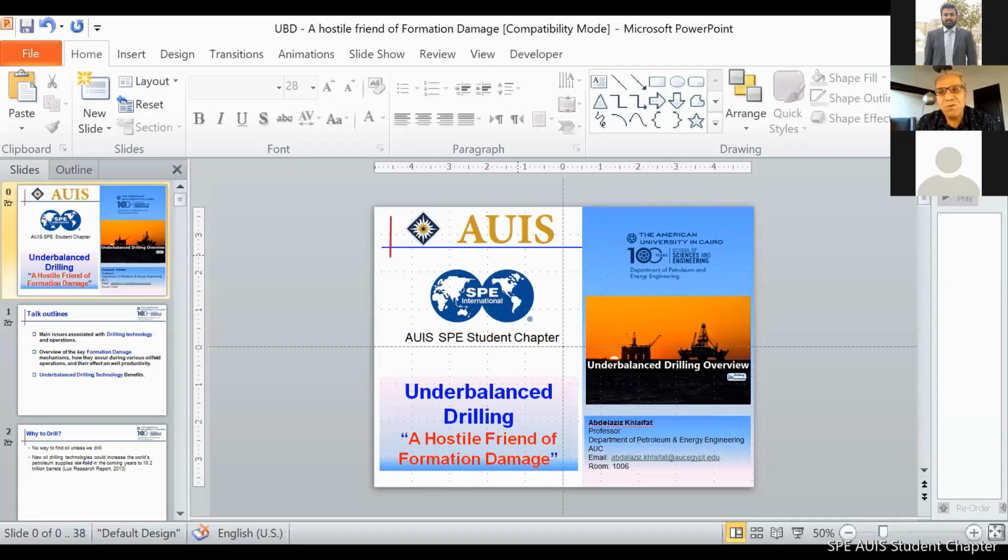Because, you know, offshore, we always take care of available space. It's very limited space. Even when it comes to separators, we have no issue, let's say, if we drill inshore to use a horizontal separator. While if we drill offshore, we have to move to vertical separators instead. So many issues have to be considered when the process is decided, but it can be applied in both offshore and inshore. But the cost definitely will be driven up when you move to offshore.